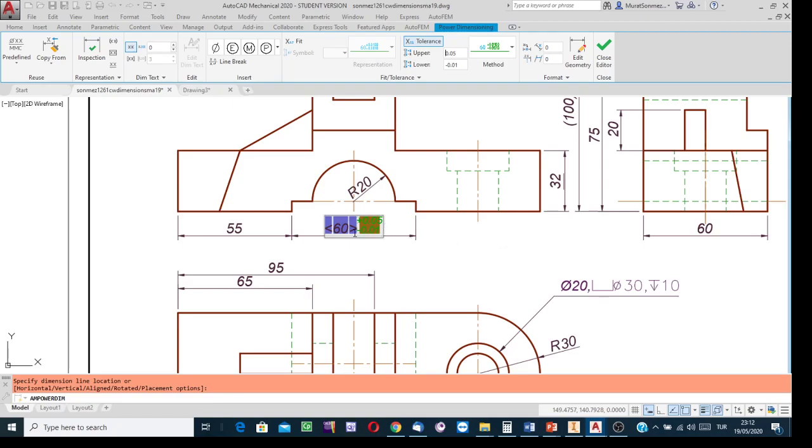In AutoCAD, to be able to show the number as a decimal number, first into this box, write the precision value as not 0 but 1. Because at the decimal part, I need to use 1 figure. Okay? And then bring the cursor to here, click. It is not automatic. Manually make a click after 60. Put the dot, and then write the first figure.